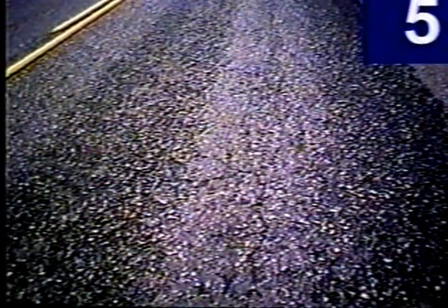Next, let's describe pavements that we would rate a 5. These are also candidates for preventative maintenance treatments like surface treatments, but there is further deterioration. For example, here you can see raveling is now extended. It's more of a moderate raveling occurring in this pavement. Another example of surface raveling, it's gone to the severe extent in the wheel paths. Severe raveling, if you're going to treat it with a surface treatment, you must get at it before it goes too far. That's why I would rate this a 5 and a candidate for a surface treatment.